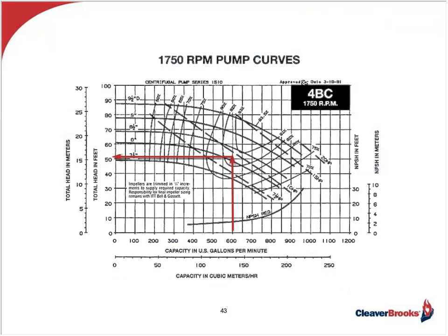Now, here's an example of what I'm referring to. And for illustrative purposes, I'm showing you a centrifugal pump with a very high pumping rate, but the curves show up better, and it's all relative anyway. So following the red arrows, you see where a flow rate of 600 GPM, and we have calculated a TDH of 50 feet.